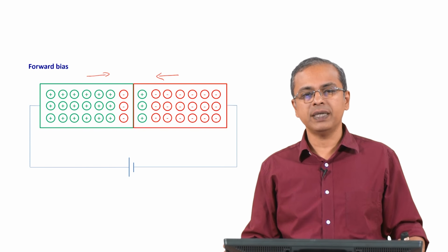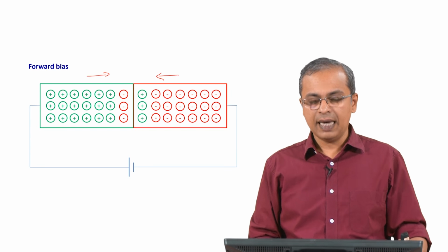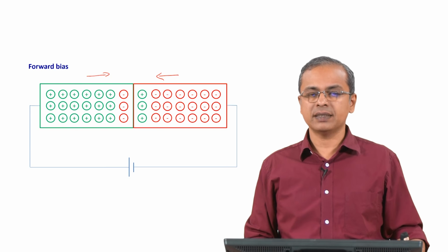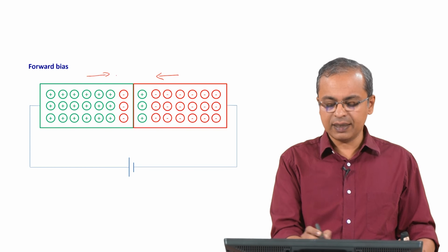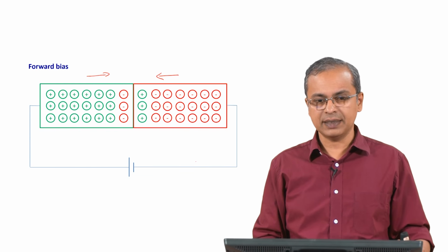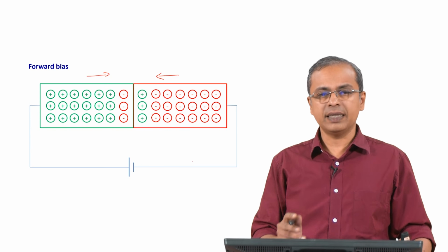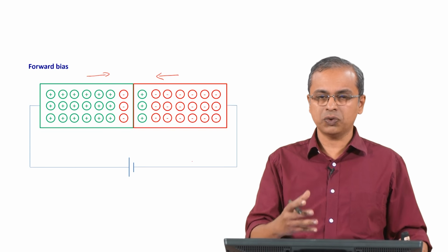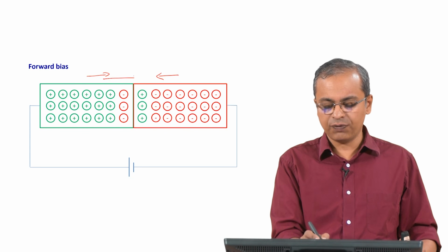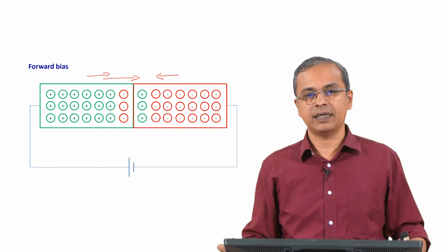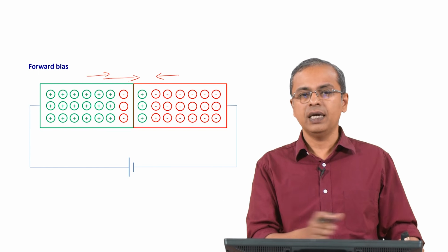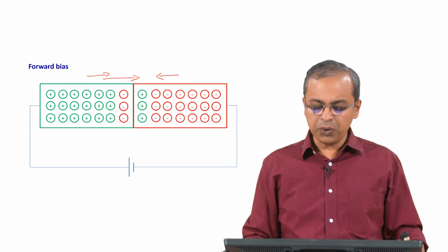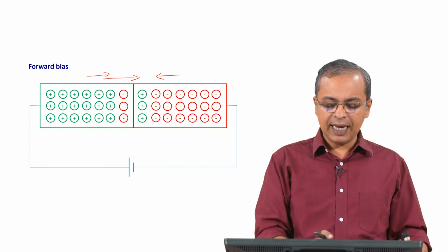So, that therefore, the space charge region begins to decrease, and once you cross the potential that corresponds to this space charge region, essentially you will have current steadily flowing through this p-n junction, and in the context that we traditionally associate current, the conventional current is associated with positive charge. This is the direction of flow of current, of conventional current. The direction of the flow of the holes is the direction of the flow of the conventional current, electrons are flowing the opposite way. So, you can think of it this way, electrons are coming this side